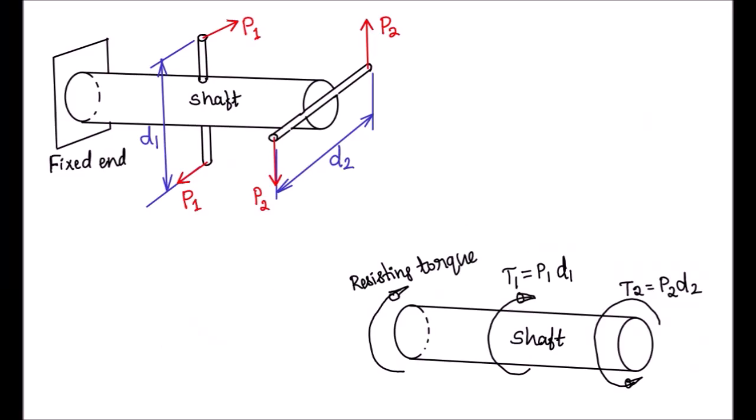This is another example of a shaft. And you can see this example, a cantilever rod fixed here and you are attaching one more rod here, maybe by welding, and you are applying P2 here and P2 here, which are separated by a distance D2, but they are equal and opposite loads. It is actually a couple. It tries to apply a moment here. It tries to twist this object. So P1, P1 or P2, P2, whatever you are seeing there, they are actually forming a torque.